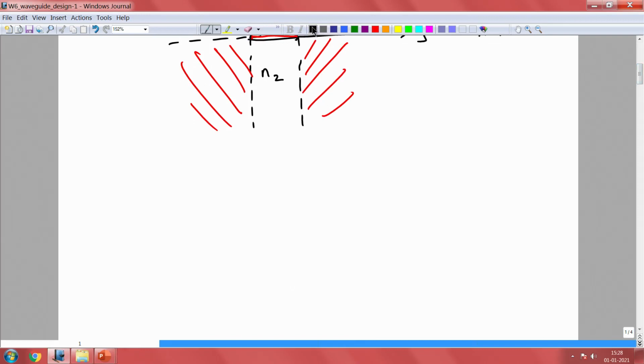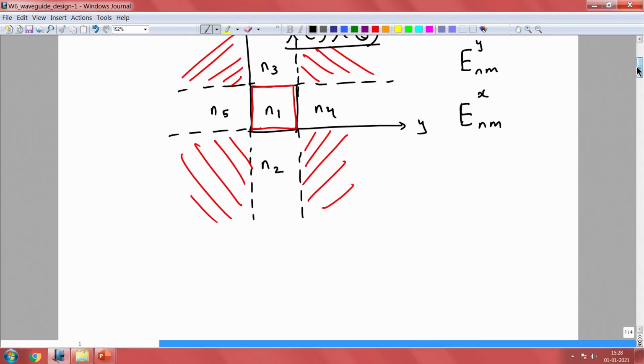We looked at this waveguide and said, okay, if you want to have a solution to this, then probably that particular wave should propagate through this with a certain eigenvalue, that is beta, for that particular solution, and you want this solution to be much above the cutoff. We saw the cutoff condition in our slab waveguides. So, you want this mode to propagate through this waveguide.